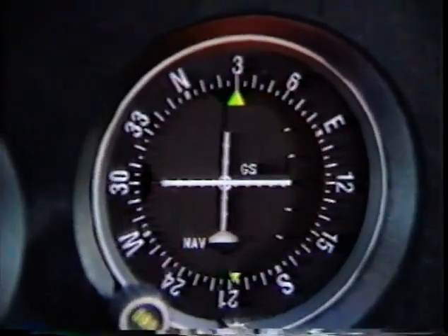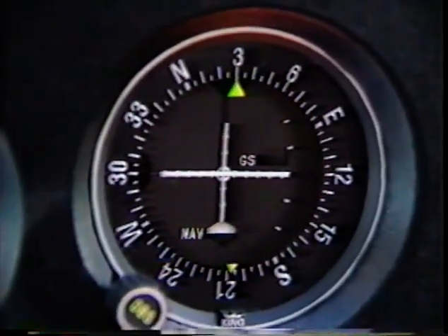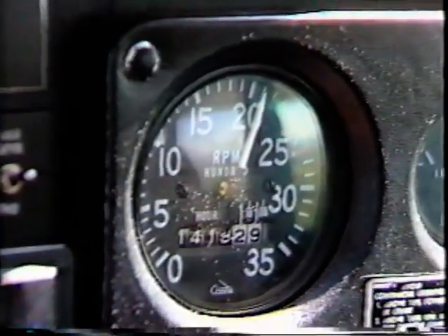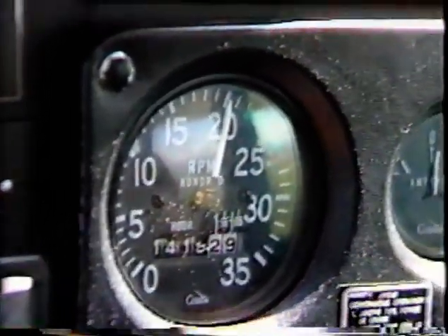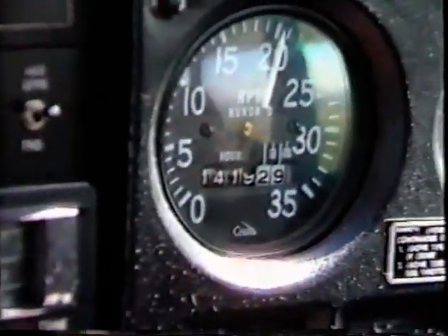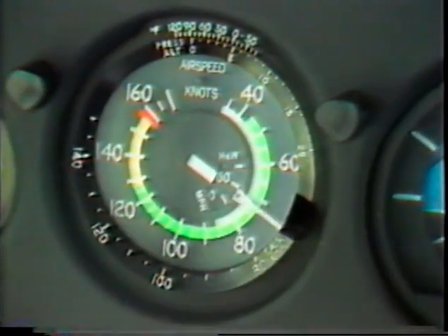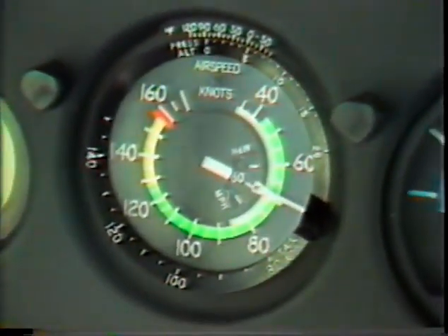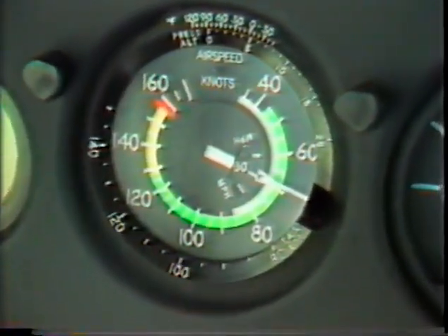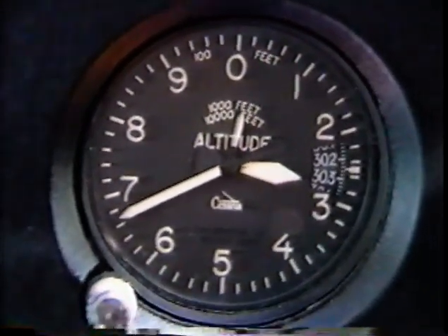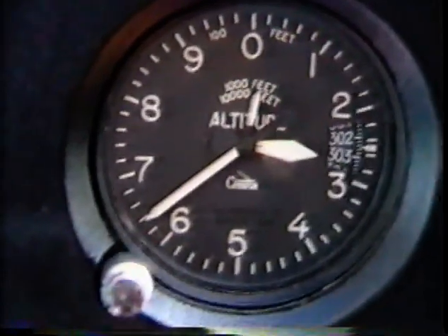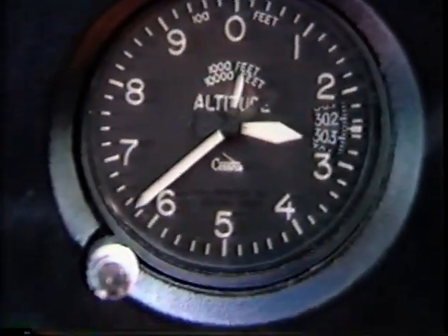If at some point during the approach a half-scale deflection or worse occurs on the glide slope indicator, the power setting should be changed 1 inch of manifold pressure, or 100 RPMs as the case may be. Otherwise, correcting such a large excursion with pitch alone would result in too much change in airspeed. The altimeter must be kept in the instrument scan during an ILS approach, and it may be helpful to periodically call out the number of feet remaining to decision height.